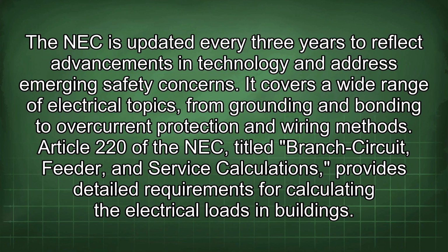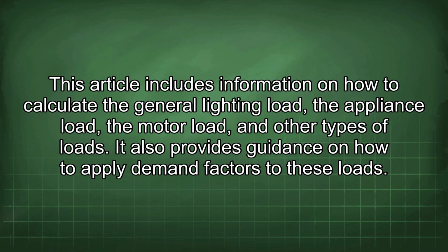Article 220 of the NEC, titled Branch Circuit, Feeder, and Service Calculations, provides detailed requirements for calculating the electrical loads in buildings. This article includes information on how to calculate the general lighting load, the appliance load, the motor load, and other types of loads.